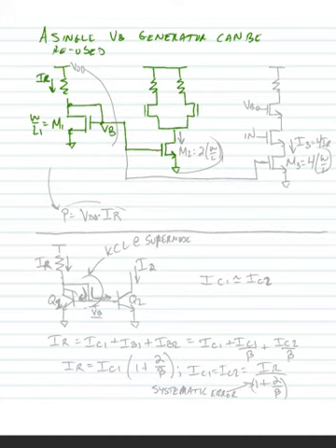So we'd send this VB over to the gate of that current source, and of course some current would flow through it. Now, of course, we might make M2 equal to 2 times W over L1, in which case twice the current would flow through this branch as is flowing in the reference branch.